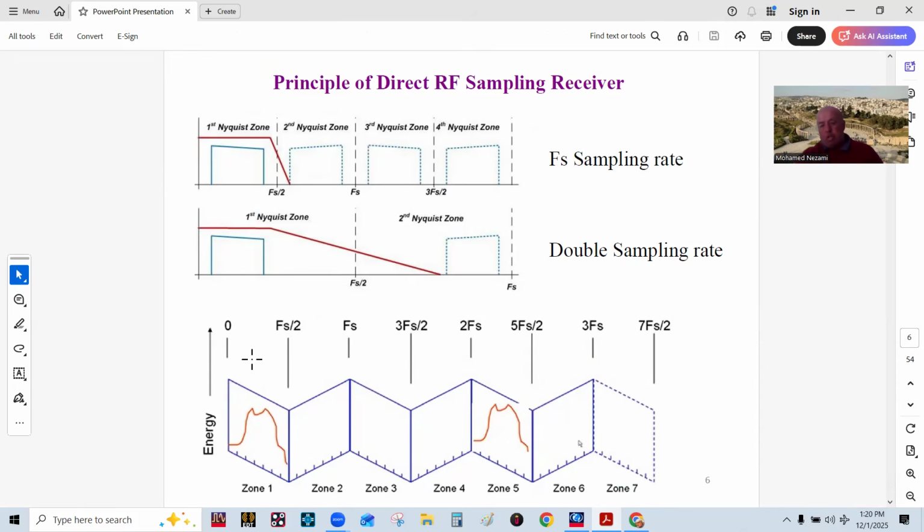But of course, the aliasing filter has to extend to see that. You can digitize the analog signal anywhere in here, and it's as if these Nyquist zones fold back and all get copied in the first Nyquist zone.